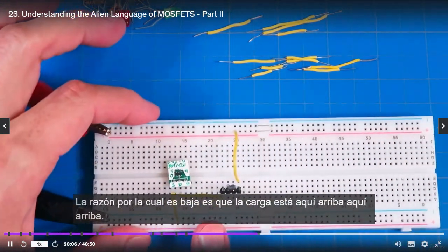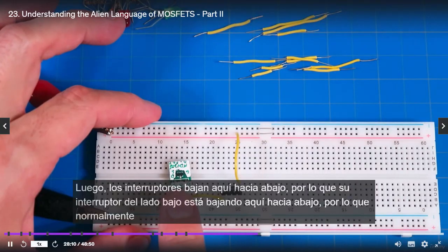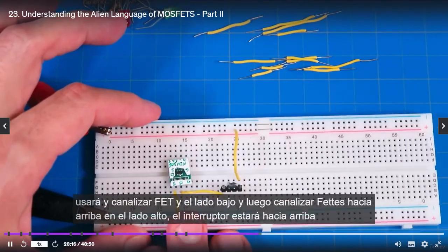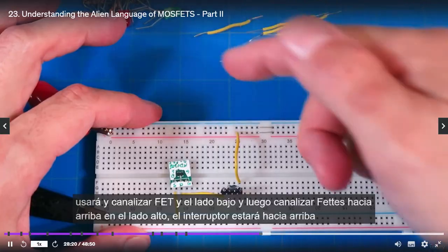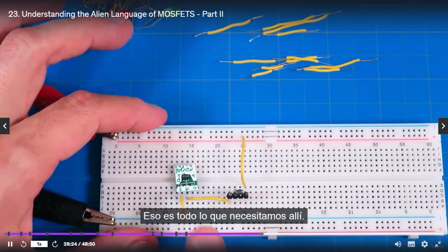The reason it's low side is the load is up here high, then the switch is down here low. The switch is switching down here low. So you'll typically use N channel FETs in low side, and P channel FETs up at high side, where the switch is up high and the load is down low. That's where that comes from. That's all we need there.